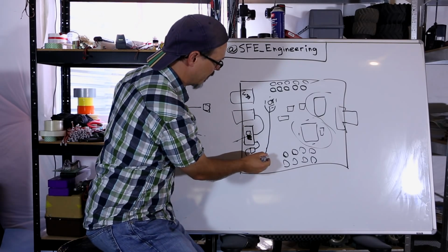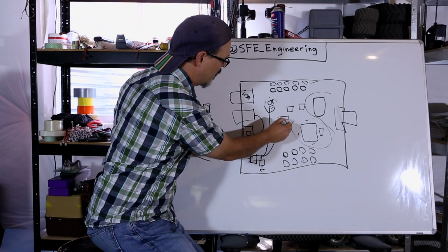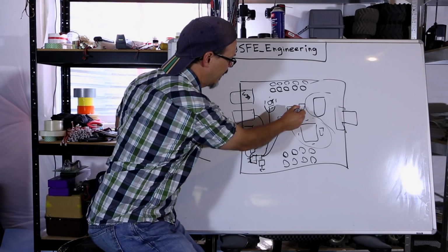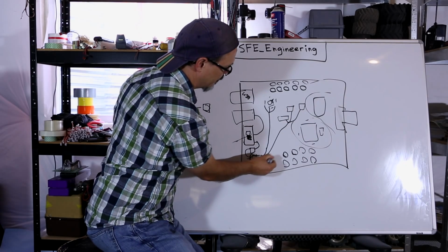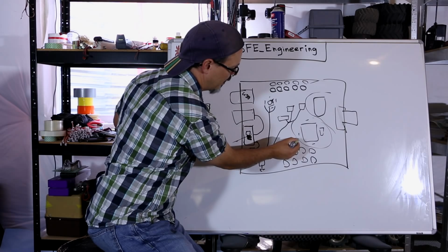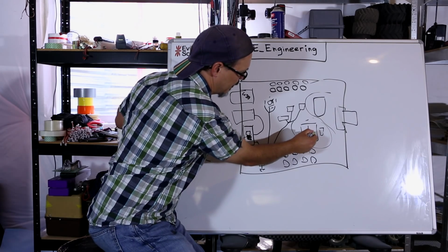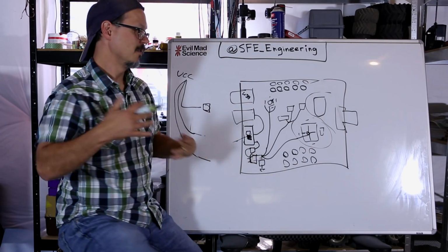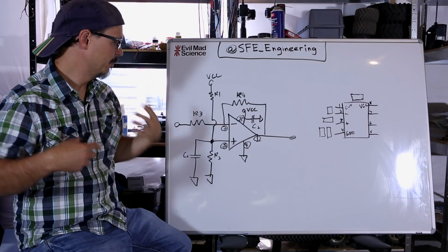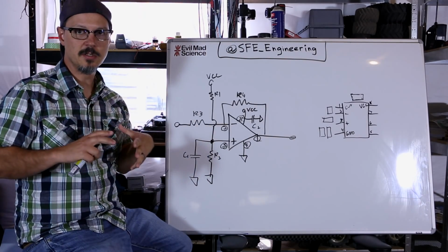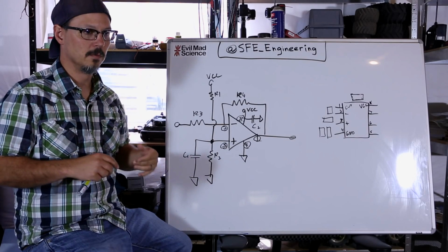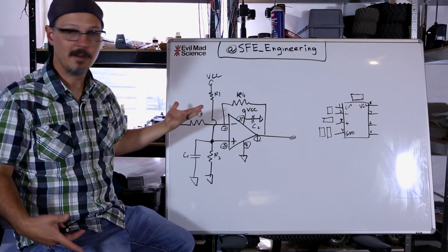And each section will go back this way, okay? And so there'll be one to the micro section as well. And a lot of times I'll run this directly under here and then feed the different power pins. So it's all very equal, okay? You want to build the circuit stages, the circuit sections. Really, you just want to follow the schematic, right?